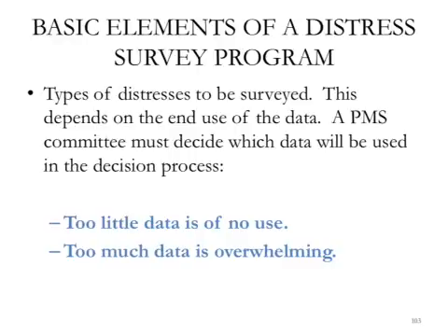For example, if we are dealing with lots of fatigue cracking, we will have to spend more time measuring fatigue cracking, its extent and severity, and even sub-types of fatigue cracking, while in another place they may be dealing with thermal cracking, and therefore most of the effort would go towards this type of distress.